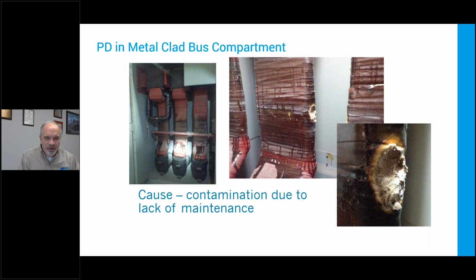If something's conductive, you're not going to have a voltage drop across it, so that same voltage drop is concentrated where it isn't conductive. It was concentrated at the ends of the separation, and you can see where the insulation was eaten into. It was in the process of failure. This was screaming out ultrasonic energy. There was no need for an algorithm or a phase resolved plot. You got near it, and it just put out a ton of noise. This was fixable, right? If they went another 6 months, maybe it wasn't fixable.